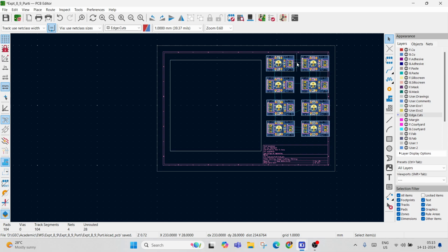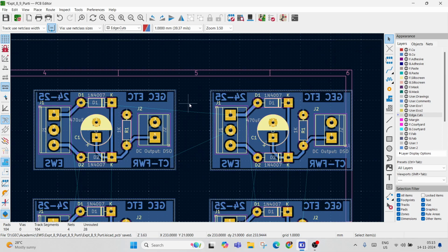So for the second travel to happen, there has to be some kind of board in between. I need at least 2 mm of board in between two gaps, or two edge cuts that the machine is going to do. At least 2 mm in between, so total 6 mm. What I'm talking about is this here. The machine will come here and perform an edge cut of 2 mm. Then the machine will go here and perform an edge cut of 2 mm.